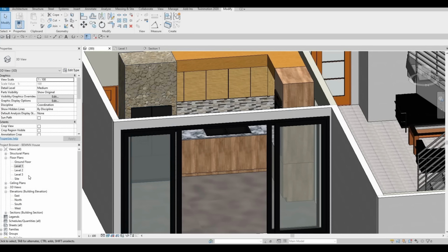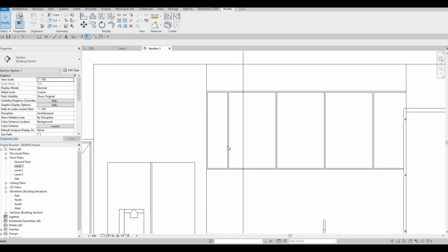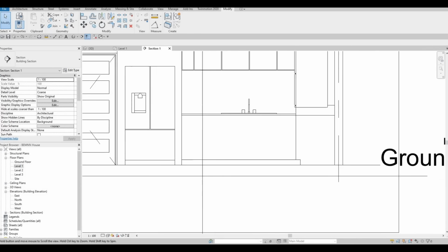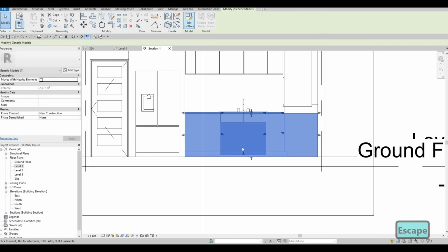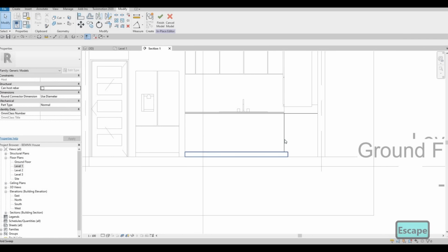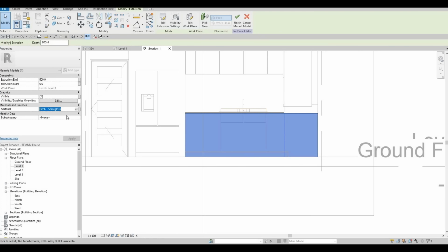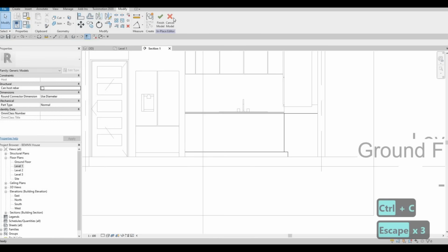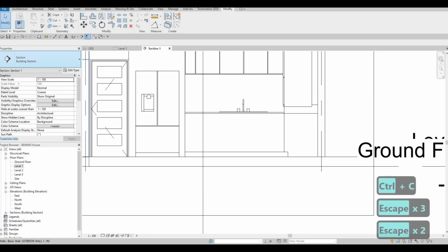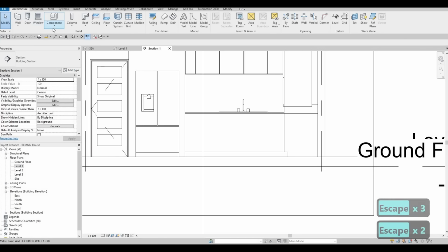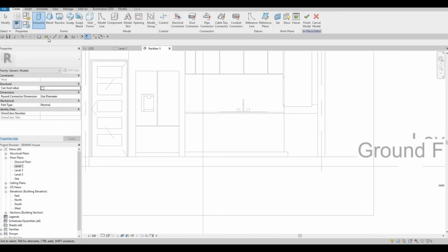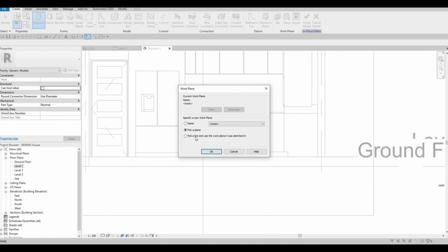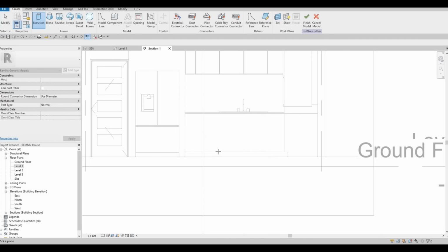then let's do the one for below before we continue on the side. I want to double check what we use right here for the below. So birch semi-gloss, so let's use that as well. So now I'm going to create a model in place, generic model, press OK, click on extrusion, pick a plane, which is this plane.